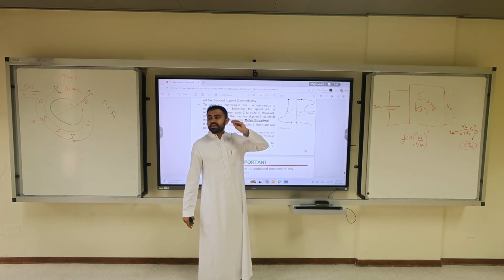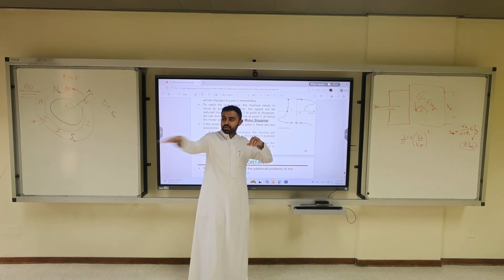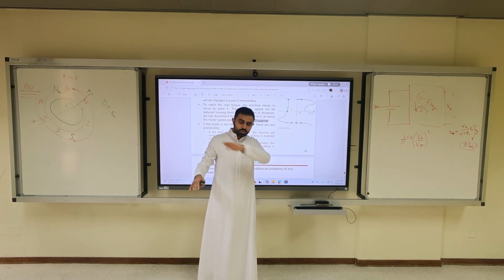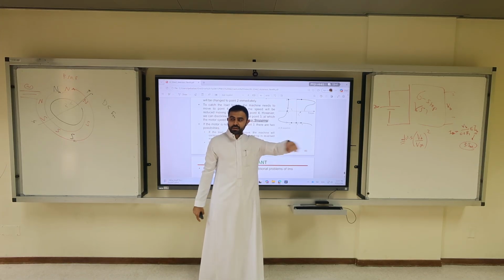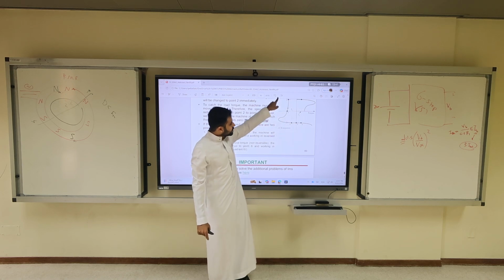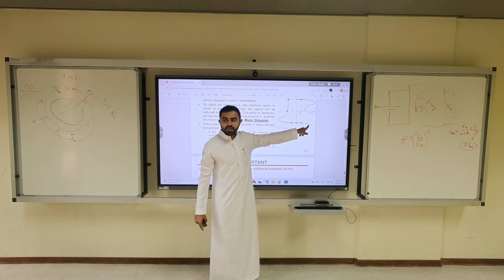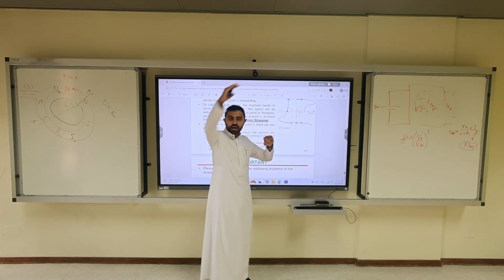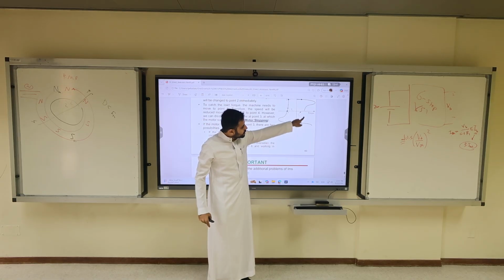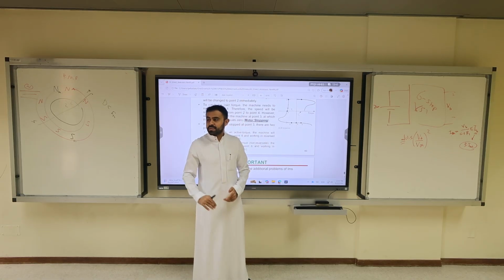How to generate electricity from non-active load? Constant torque. Load is always constant, fixed. You have to go through counter current and then go back to quadrant 4. If you have an active load, car going up and down, you can go directly here. Just increase the speed of the slip.